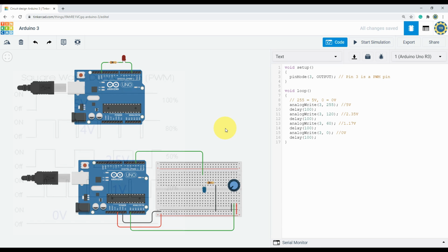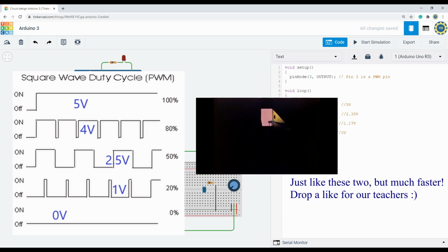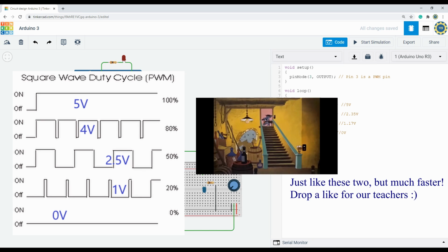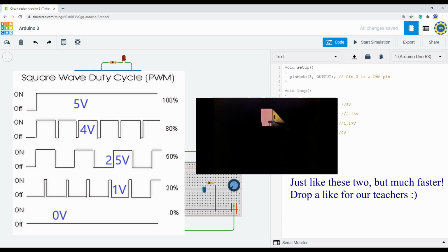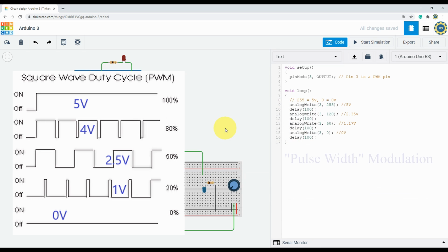Arduino uses pulse width modulation to control the output voltage level. The PWM technique lets you set the voltage level by quickly turning the LED on and off continuously. This happens so fast that we don't see the LED blinking. Instead, we see the brightness of the LED drop. By adjusting the time delay, aka the pulse width, we can make the Arduino output analog voltage.